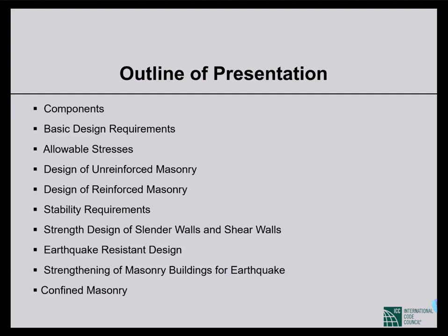If you have a very small boundary wall without any continuity, with stiffening only at one end and the other end continuous, then you have case 5. Case 3 is if you have a very small boundary wall with stiffening members only at both ends. If you have stiffening members at certain spacing and the boundary wall is continuous, then you have case 1.